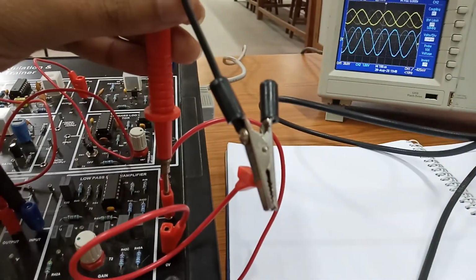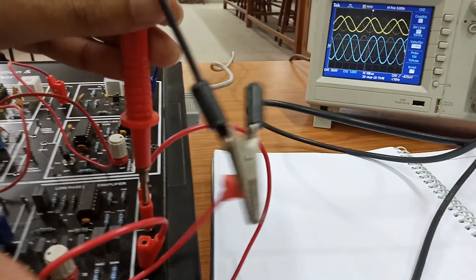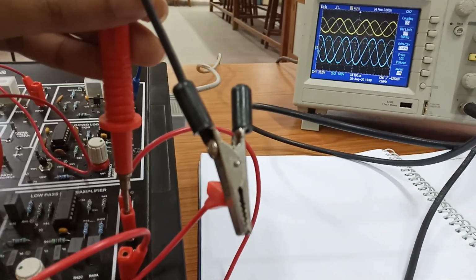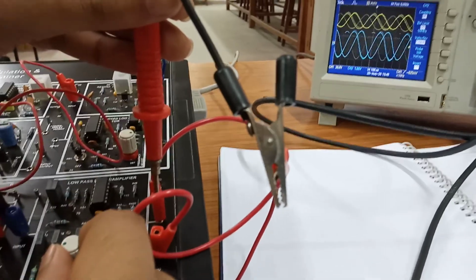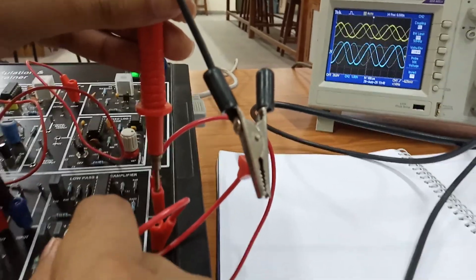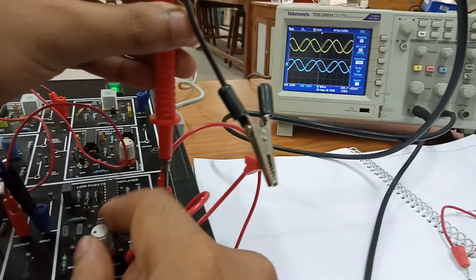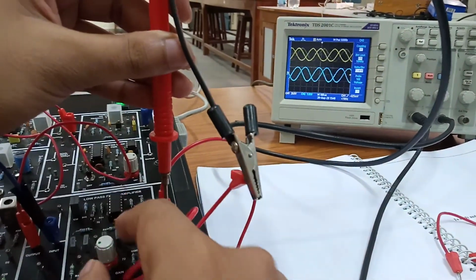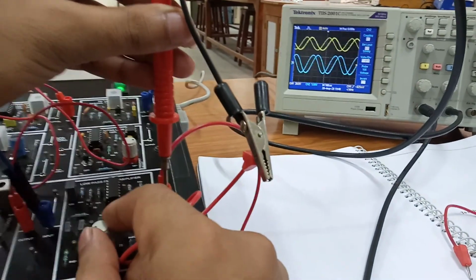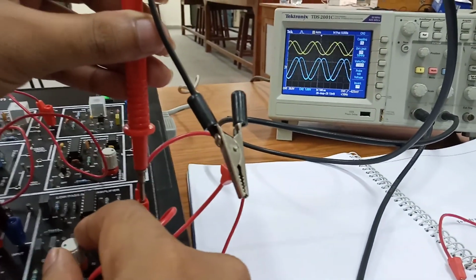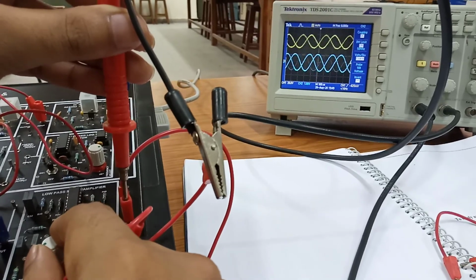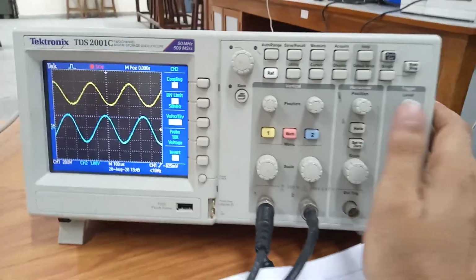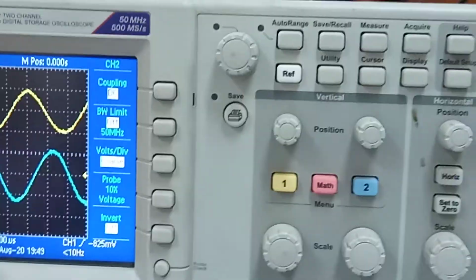So this is for adjustment of gain at the low pass filter. If there is any amplitude distortion, or the amplitude is getting reduced because of the demodulation circuit, then we can adjust the amplitude from here, from the low pass filter. Here we have an amplifier with a gain, so that we can amplify the amplitude of the demodulated wave.